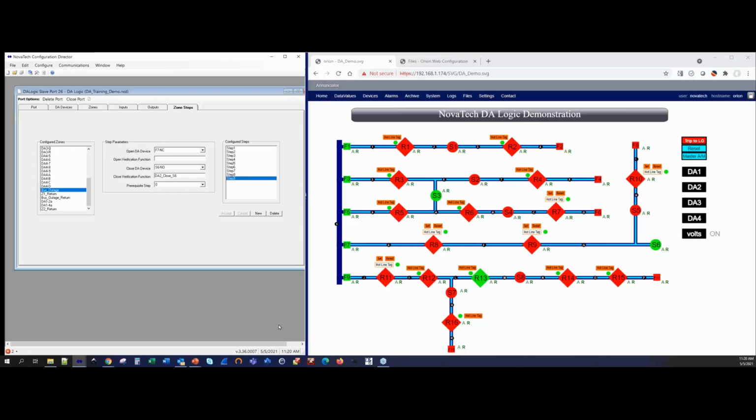And you may have DA go ahead and do the switching to do an automatic restoration as much as possible. But during the repair, you might cut jumpers, you might open switches that are not being automated, so a manually operated line tension disconnect or something like that that is not being monitored by the DA.